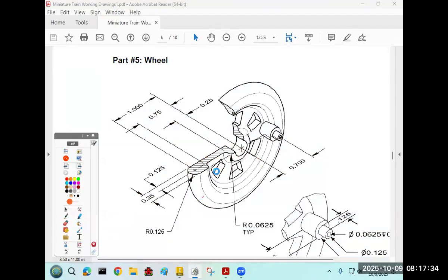But it's sketchier than you think, so to speak, because we've got these little rounded edges that you can tell what they are because this dimension points to it, and it says TYP, which is short for typical, and it means that this, and this all have this dimension. And it's an R, which means it's a radius. You know it's pointing to this curved surface. There are actually 4 separate curved surfaces here that we will get to, fillets.